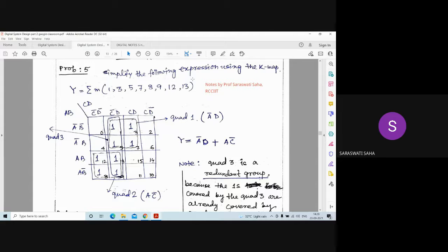Ma'am, 4. Why? Ma'am, because 13 is present here, the maximum min term, and to represent 13 in binary form, a minimum of 4-bit combinations is required. So now y is a function of A, B, C, D.